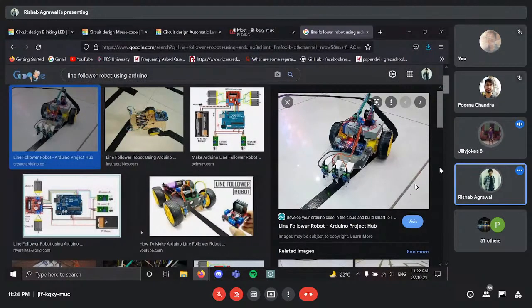Basically, just repeating the problem statement so far, there will be two LDRs connected to two motors using the motor driver. Based on the inputs of the LDRs, the motors have to move correspondingly, assuming that the darkest point is the line in the middle that the car is trying to follow.